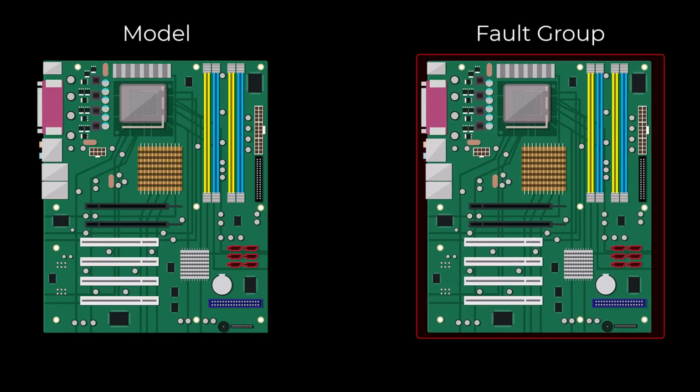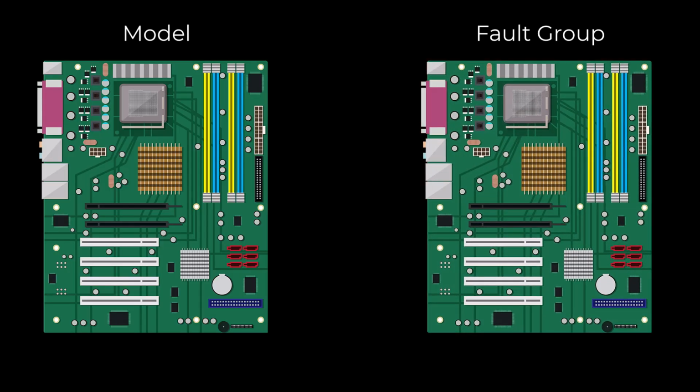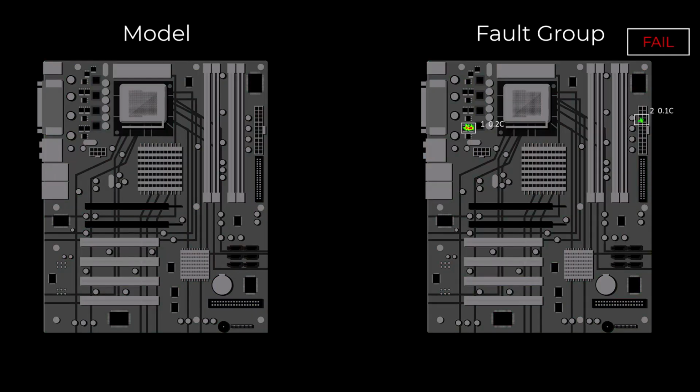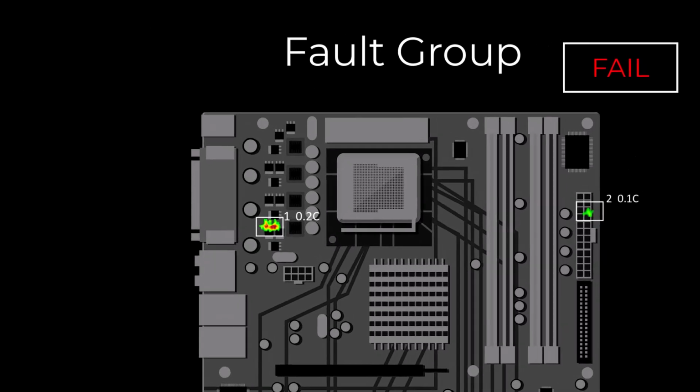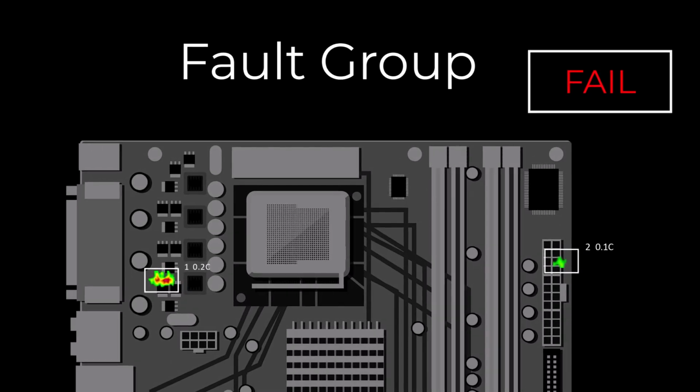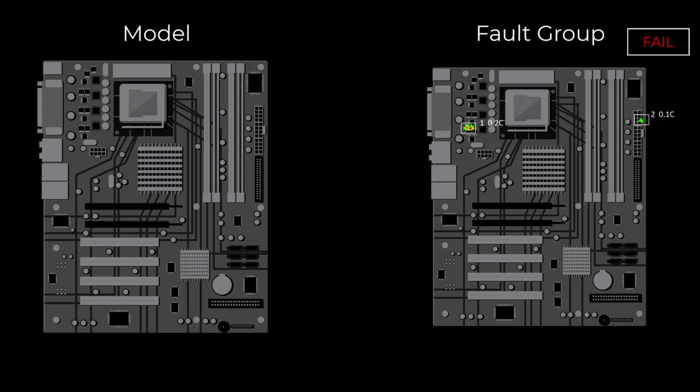After the sequence has been saved, it is compared to the model and the results of the comparison are displayed. Areas on the device that are outside the acceptable range of the model are displayed in color with pixel values indicating the magnitude of variance from the model. Each of these areas, called fail sites, are enclosed in a rectangle and are numbered consecutively according to severity.